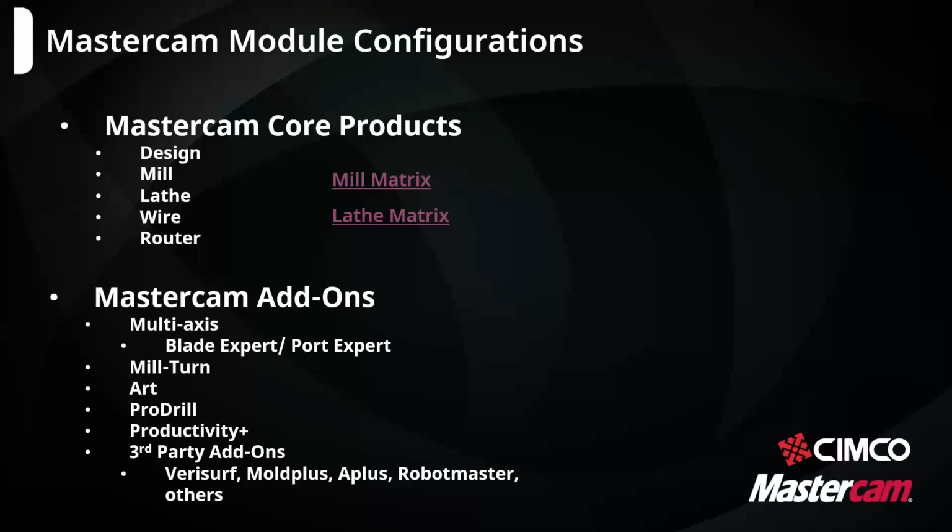The ProDrill product actually used to be a third-party add-on, but it was integrated into Mastercam a handful of years ago. That's really geared towards customers that are doing a lot of hole drilling, especially with custom form tools. So think of a hydraulic manifold and similar type parts where you really need to get into multi-step, multi-stage drilling.